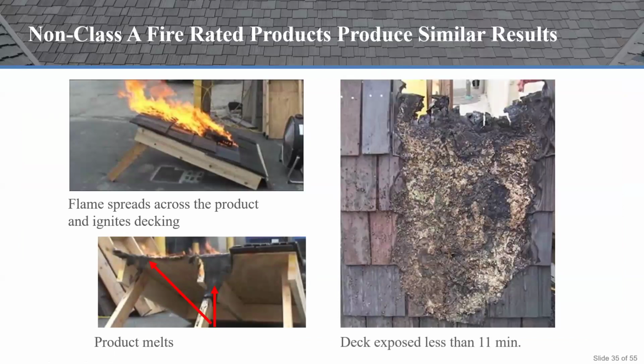Whereas with a composite roof, you expose that open flame to the roof, and the class A material in the composite tile is actually going to be self-extinguishing. It's going to put out that flame, so it doesn't give the flame the opportunity to spread across the roof deck, ignite the decking, and then cause even bigger problems, right?